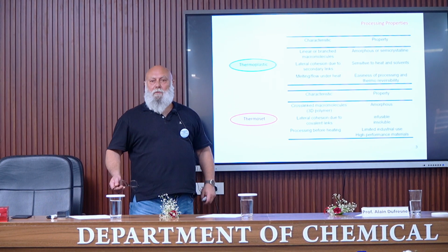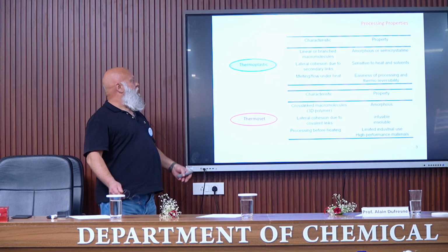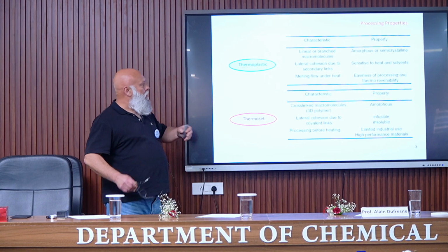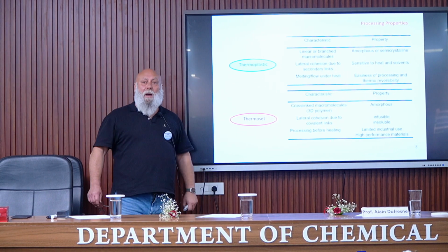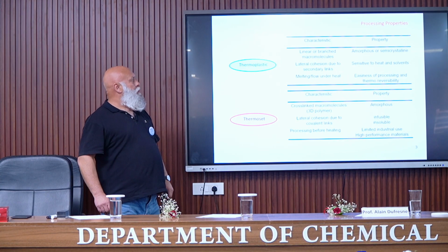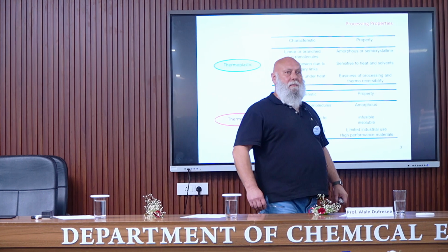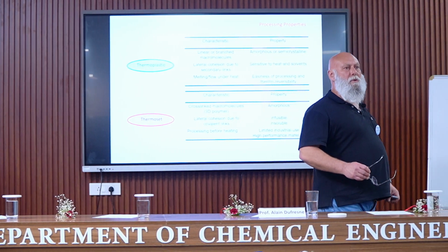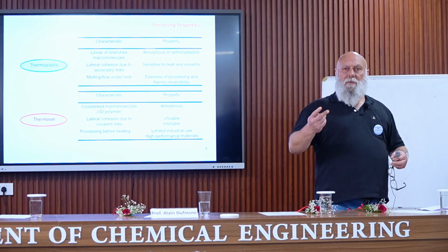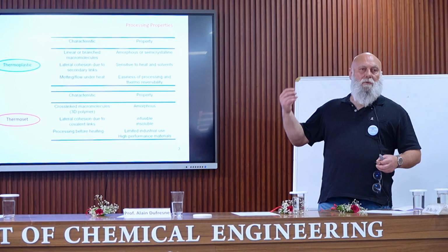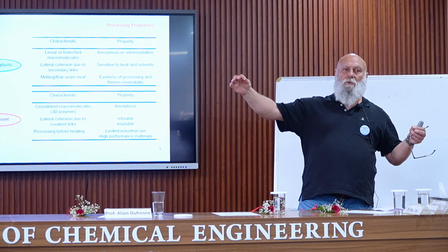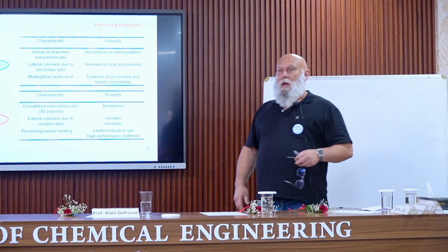So there are different parameters that can impact the ability of the polymer to crystallize. But even if the polymer crystallizes, it is always only semi-crystalline. There are two reasons for this. The first one, we are considering very long molecules, macromolecules. And of course, we have some entanglements between these macromolecules.